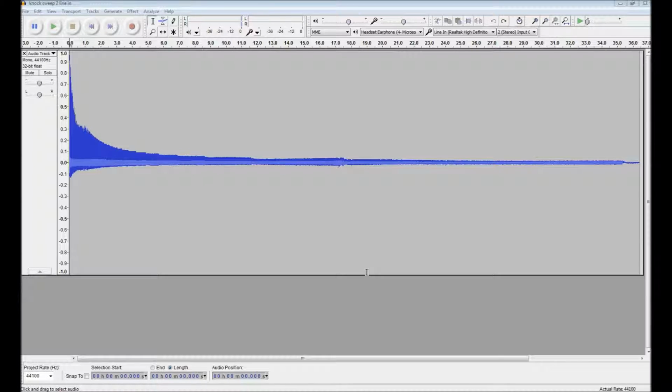Hello all, I just wanted to show you and explain some things about the signal that is fed into the knock pin on the ECU and how it's done basically. It's a sweep that runs from 100 Hz to 35K, and the window is around 10, it's exactly 10 milliseconds after each ignition event.